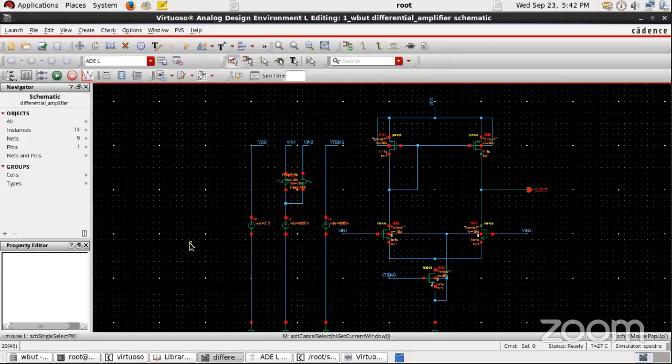Yeah, you can try that. Then instead of going for two voltage sources, we can have one DC voltage source, which will be sufficient. Exactly. Or you can go for a current mirror, which will also be a good option. Instead of this VT bias, you can implement a diode-connected transistor on the other end, and that gives you the current mirror. That gives you the bias voltage required for the circuit, the current sink.